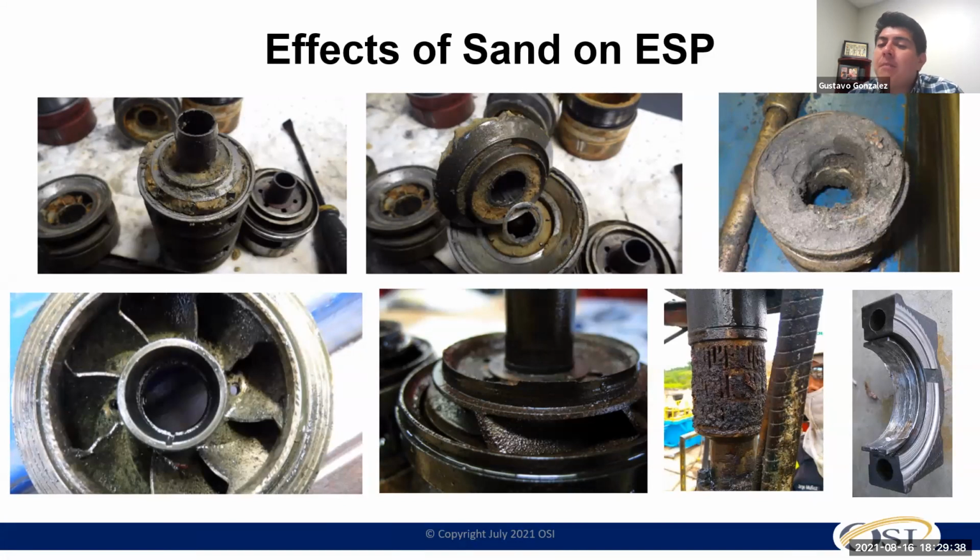Again, it goes back to how much solid and how much pressure drop, and which stage of your pump you are in. Either you're in a brand new well that you're lifting 5,000, or you're in a well that you're just producing 350 barrels, not an unconventional, or a water flowing well. This screen is normally designed for lower rates and wells that don't have high scale precipitation or iron sulfide.